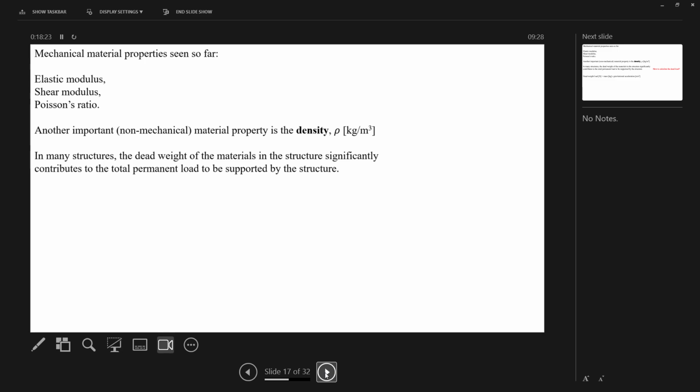Remember me in first year, and I brought out a small section of I-joist timber, and I said this is very, very light, but this is stronger than the larger piece of wood that I had, and it was a glulam beam. I said this I-joist is stronger than this. They were roughly the same size, section-wise, and that was because your beam, if it was a full-length beam, the I-joist is much lighter, and therefore it's not having to carry its own self-weight over that long span. And we then talked about the second moment of area, and you learnt more about that from Juan later on.